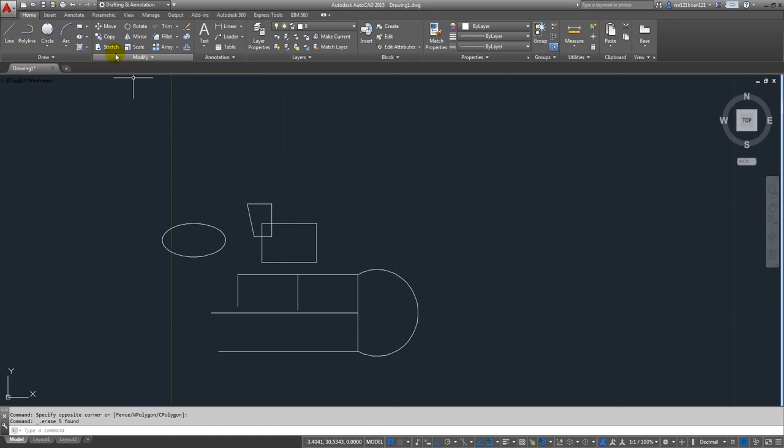Okay, for scaling we select the object, we press enter, and we move to the scale we want. Usually if you press 1 and then you press enter, the object will not scale because it's the scale it is. But if you press scale again and you move it, for example, for 0.5, it will be 0.5, it will be the 50% less size right over there.